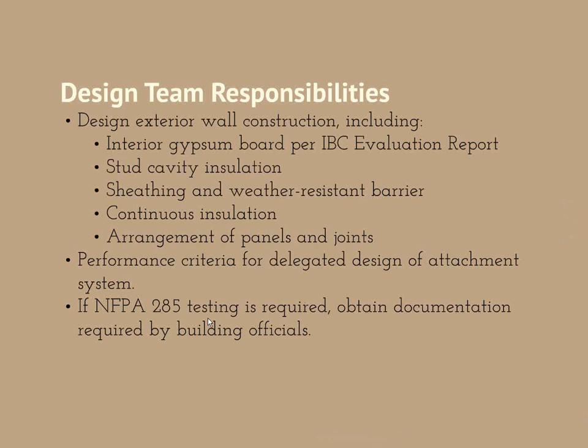Okay. So, I look at this and we see stud cavity insulation, and I have to stop and think. One of the very first projects I did that looked at continuous insulation had to have been from the early 2000s. And actually, we had no cavity insulation, and this was for a Penn State project in State College. And when I first saw this, I was absolutely amazed that it was from a design architect coming out of New England. And maybe we really need to stop and go back and look at this whole thing again and really push all of the insulation to the exterior and forget the stud cavity space. There are certain advantages for that.